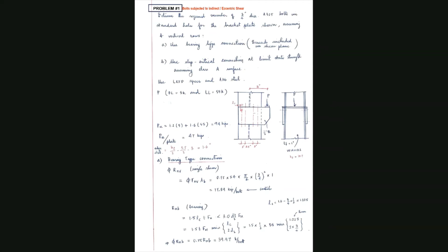Okay, so here I have taken 3 inches, and now this is the next important step, because here we need to calculate a term called the polar moment of inertia J, which is the summation of xi square from 1 to 20, because there are 20 bolts, plus the summation of yi square from 1 to 20.